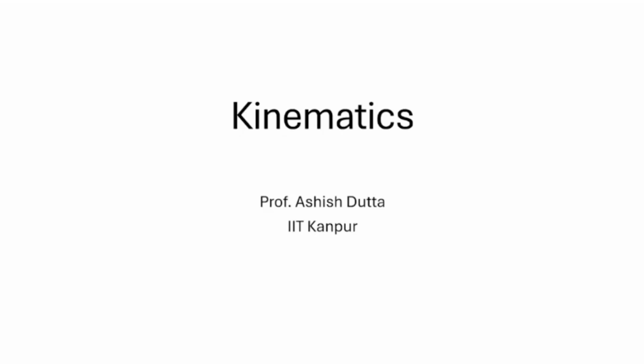So today, first we'll start off by very quickly revising the DH parameters of a Puma robot, and then we will move on to the forward kinematics and inverse kinematics. Again, we'll start off with simple examples, and then we'll move to more complex industrial robotic systems. So today we'll first revise the DH parameter assignment for a real industrial robot, and then move on to forward kinematics, to be followed by inverse kinematics.